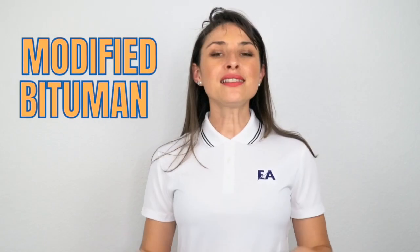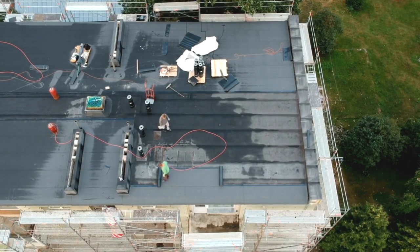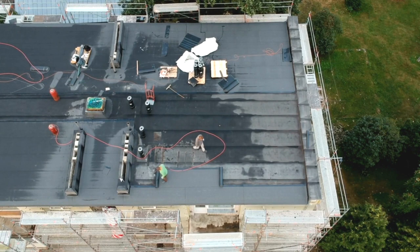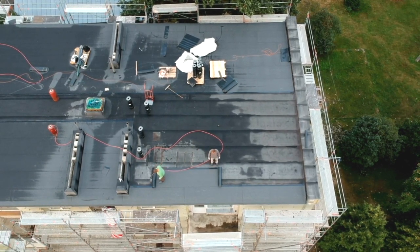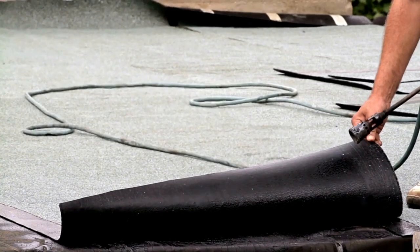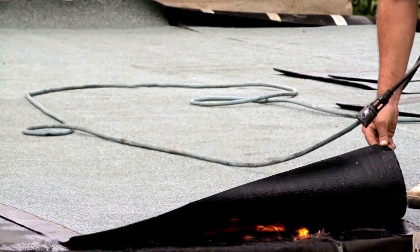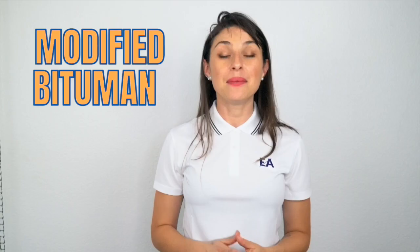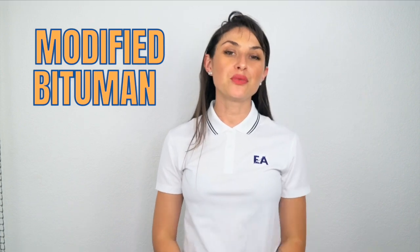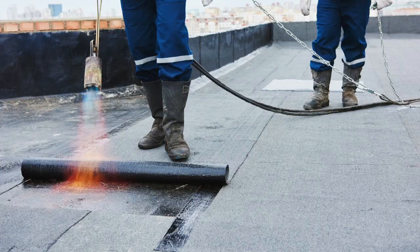Modified bitumen. So this type of material actually began in Europe in the 1960s and didn't really become so popular in the US until the 1970s. This is an asphalt-based material and it's designed to withstand the harsh exposure to the extreme environmental elements. However, the popularity of more modern single membrane systems, such as EPDM and TPO, has reduced the demand for modified bitumen roofing.